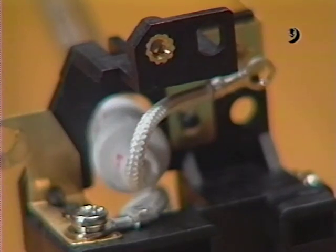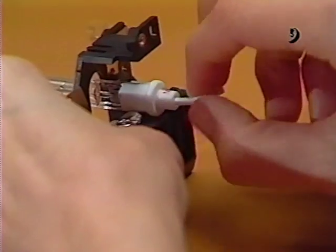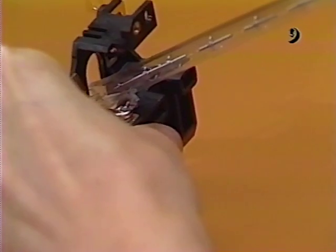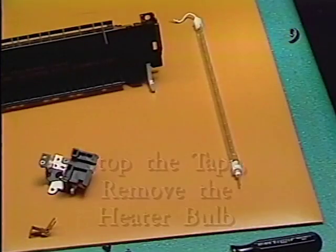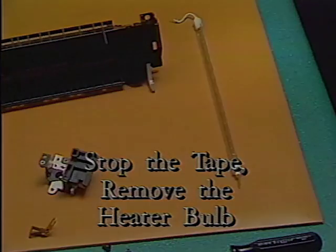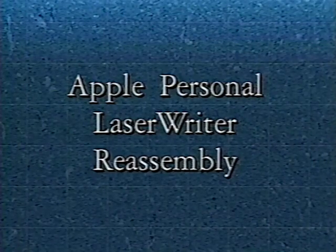Set the spring leaf aside. Finally, carefully remove the heater bulb from the left connector holder. Stop the tape and remove the heater bulb. This concludes Apple Personal LaserWriter Take-Apart. Now reassembly will be demonstrated.